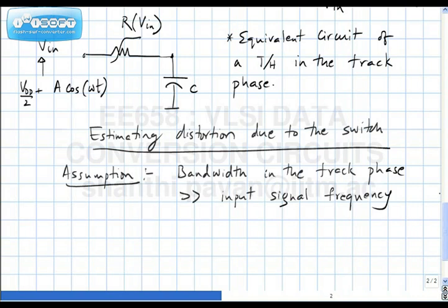If there is no current through the resistor, then regardless of how nonlinear the resistor is, there is no voltage drop across the resistor, which means that the output and the input must be pretty much identical. So the culprit therefore is the current flowing through the resistor.